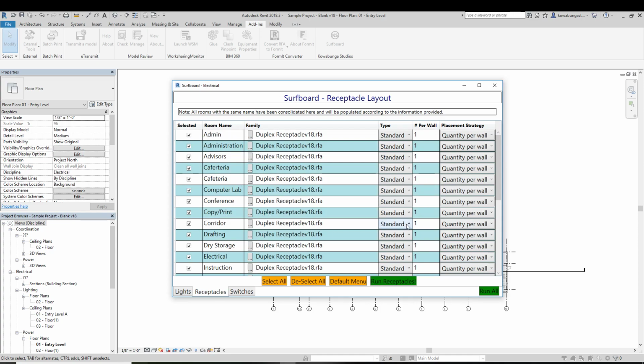For the corridor walls, this is what I recommend. How Revit creates walls, it breaks up those walls during the construction process or the modeling process, so how the architects put them in. A wall that perpendicular or otherwise intersects another wall might create 2 walls. So this works actually pretty well for the 50-foot spacing of convenience receptacles within corridors.